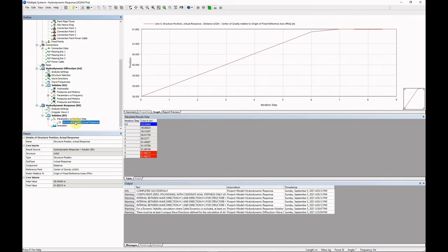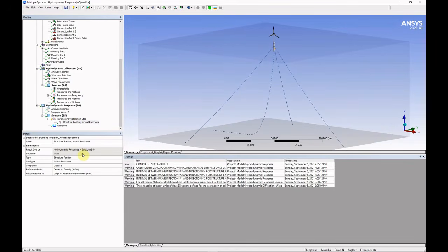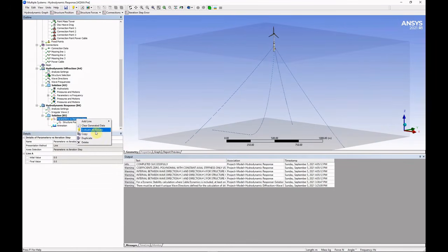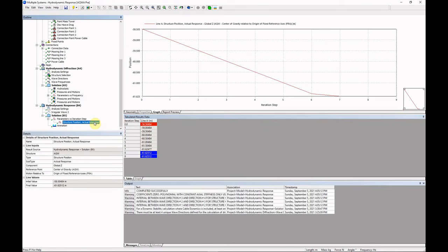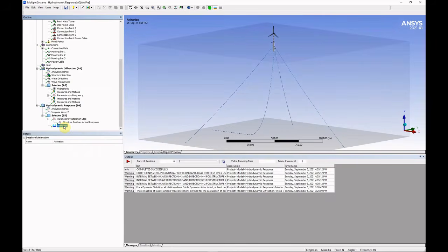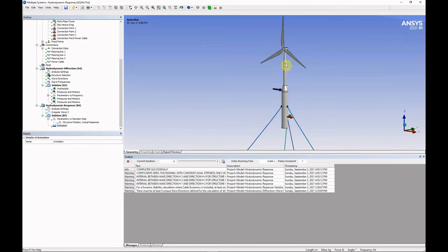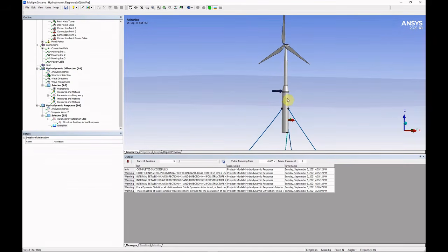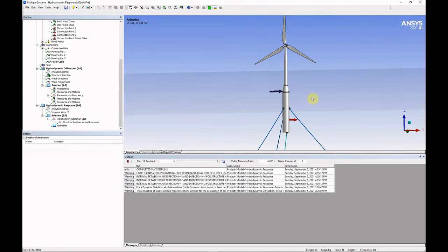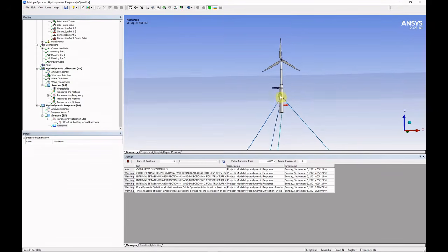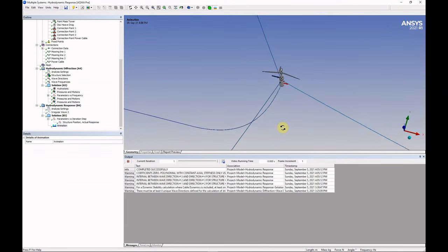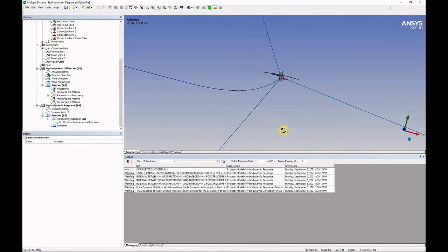The solution for position can be changed to the global vertical axis. We see that the platform sank some meters due to the mooring and the cable forces. The animation of the motion shows the platform is moving downwards and slightly to the side. It can be due to the wave being not so small and drifting the hull. There's also the possibility of some imprecision in the mooring design and horizontal forces caused by the power cable.